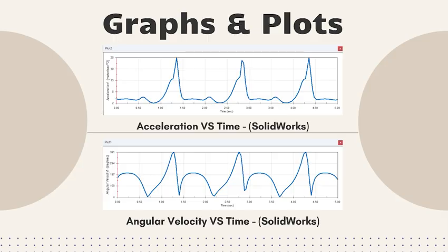This acceleration plot highlights the dynamic forces acting on the wiper linkage. The spikes represent the moments of highest mechanical load, especially during direction reversal. These are the regions where the motor needs extra torque and the joints face maximum stress. This visualization helps us pinpoint exactly where the mechanism is most demanding. Studying these peaks allows us to design stronger components, reduce vibration, and ensure the system remains durable over long-term cycles. Essentially, this plot tells us how the mechanism feels the motion, not just how it moves, making it a powerful tool for engineering decisions.